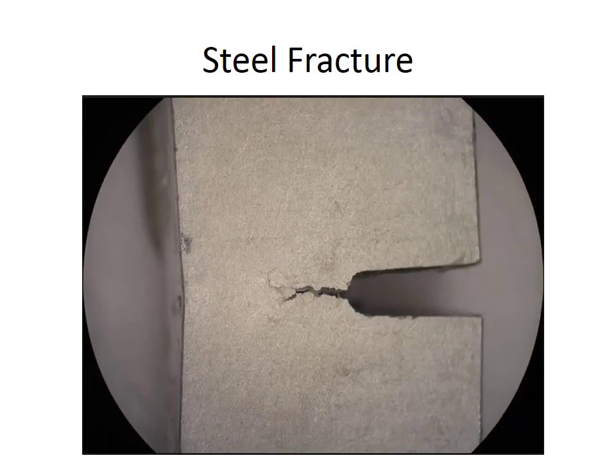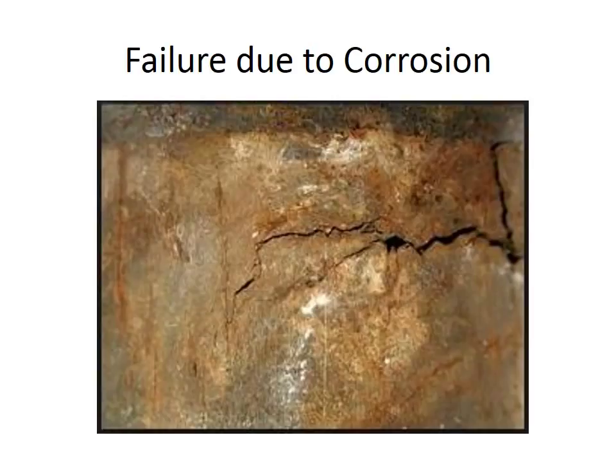We can now see how high strain levels in certain areas could be problematic from what we know about fractures and fatigue. As corrosion increases, cracks will grow at stress concentrations. If the crack length reaches a critical size, the steel will fall victim to fatigue failure. To avoid complete failure of stainless steel, parts of the evaporation system would have to be regularly replaced or repaired, costing time and money. Perhaps there is an alternative to stainless steel that avoids the issue of stress corrosion cracking.